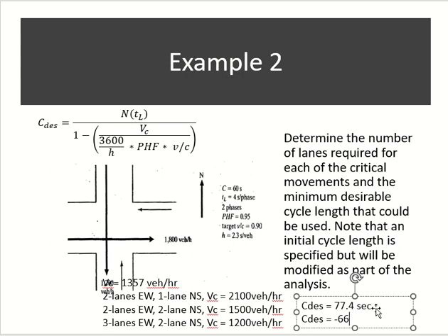Okay? So we mentioned 2 phases, right? That having 2 phases is very difficult. Why it is difficult, you can see in this example. First of all, you see volume going from west to east. Do you see the other direction? No. So this is one way. Same thing north-south, right? One way. Do you see any turning? No. You see how many restrictions we have to apply. Make both the roads one way, make the turnings, bend as well, and so on and so forth. So this is why 2 phases is not practical every time. Having more phases becomes necessary.